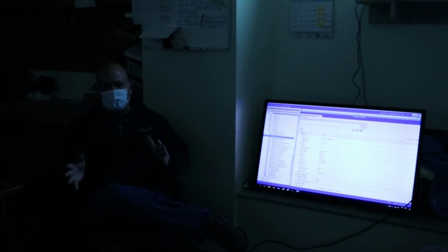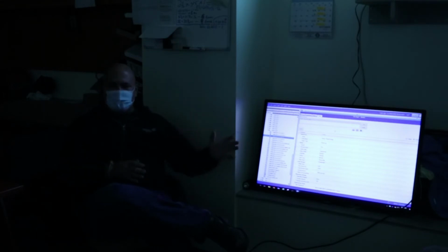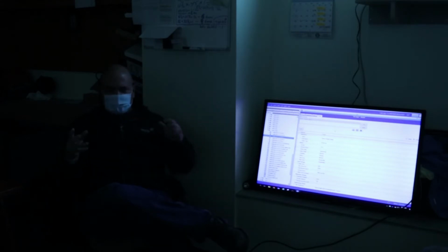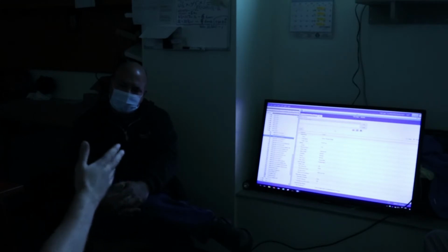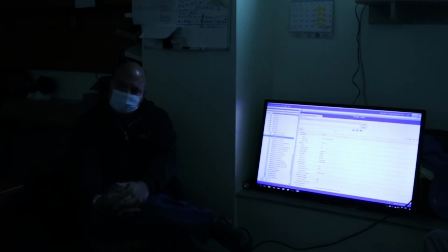Depending on the day though. If you're on a day where you use an economizer first, and your outside air is not particularly cold, I can understand it taking a little longer to get there. But for example, you say about a 5-degree difference for the machine, about 2 hours is like a normal time, right? Or about that. 2 hours seems a little bit excessive to me.